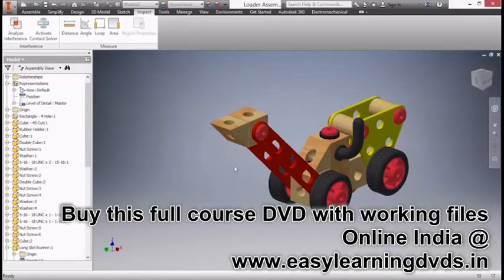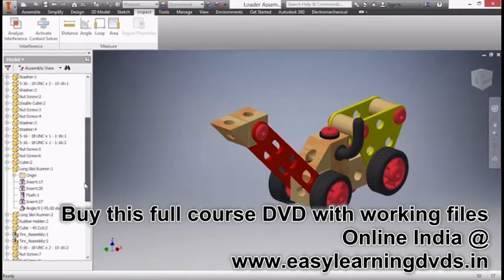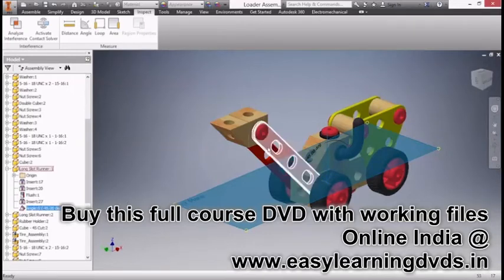I would like to have it come down a little bit or actually go up higher perhaps. I just want to check that range of motion to make sure it makes sense. Now you can probably look at this model and say it's going to be okay, but let's just take an example here. If I scroll down to the long slot runner 1, I have an angle of negative 45 degrees, maintaining a geometric hold to keep that bucket raised at 45 degrees. So if I come in here and try to pull on this, it's not going to come down.